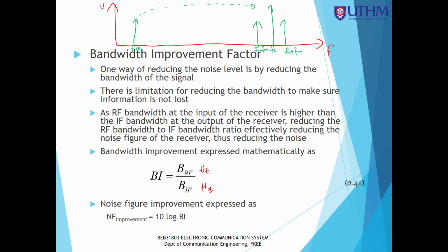When these signals arrive at the receiver, we want to do the demodulation process to get the original frequency signal. But in the receiver, it is not directly converted into the modulating signal frequency. Instead, it will down convert the frequency into an intermediate frequency. How does the intermediate frequency look? It will look like this.